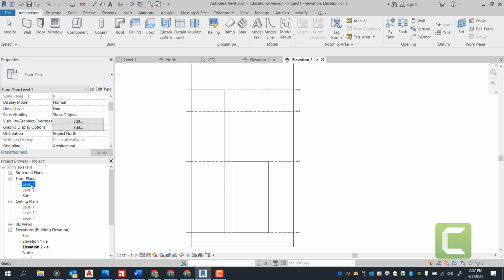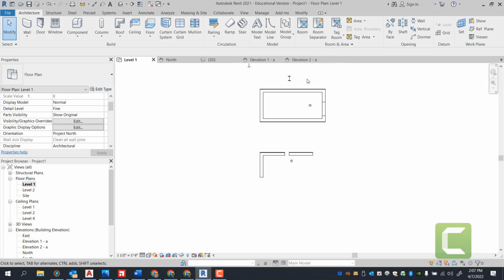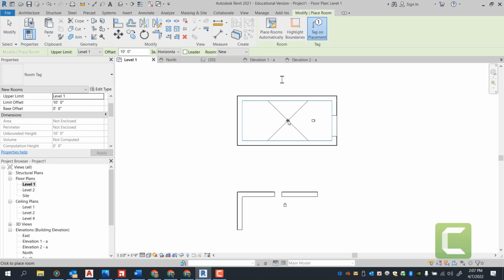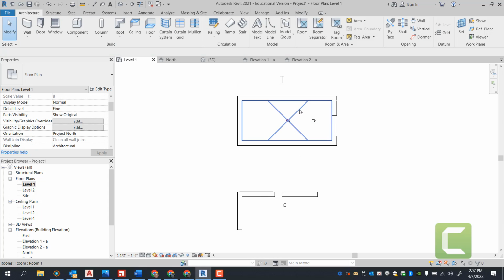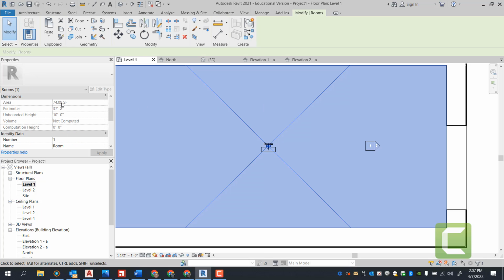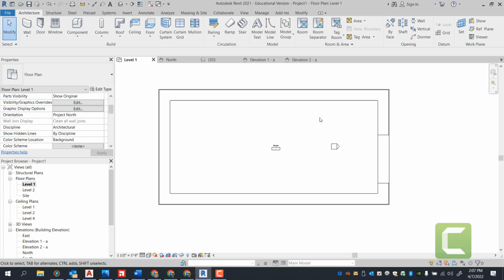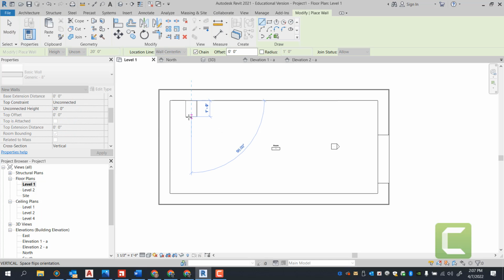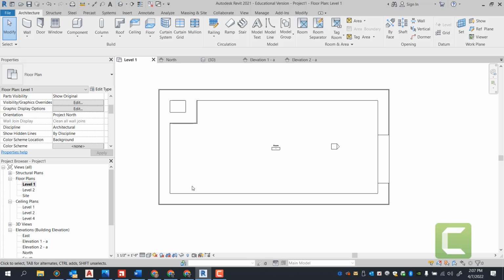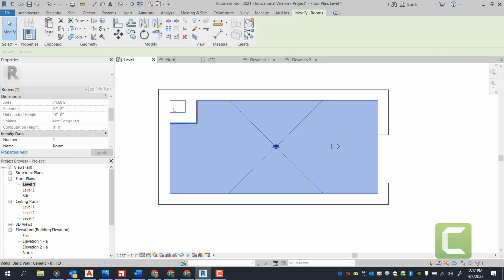Rooms. Yeah, so if I go under levels, rooms are only created in closed spaces. So I can create a room, and rooms are X's. And when you create a room, right, you have to hover in the room and find out where this X is. When you click on that, it'll give you the square footage, it'll give the area, it'll give you that room information. Now, if you interrupt that room with any type of walls, and I know you probably faced that question before, and you hover around this X again, rooms are kind of smart. They will figure out that's the enclosed area.